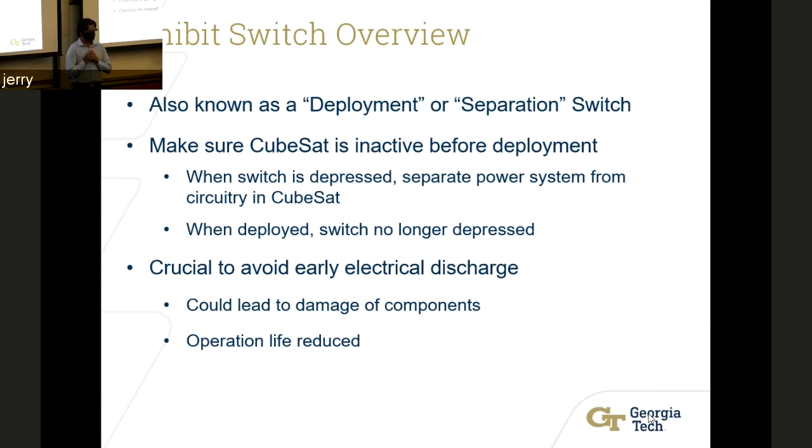Another issue that could arise if power is continuing to run while we're launching is that our operational life would be decreased. Our battery has enough power to supply our components, and if we use some of that battery life while we're launching, when we don't actually need to run anything, then we just decrease the amount of time we can do something useful after launching.